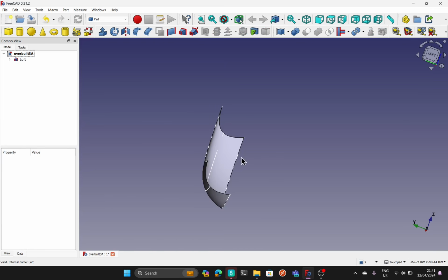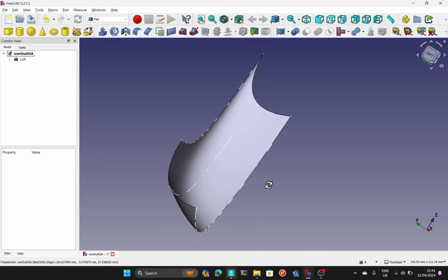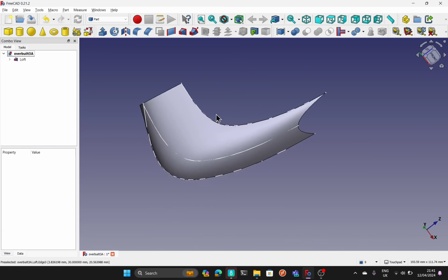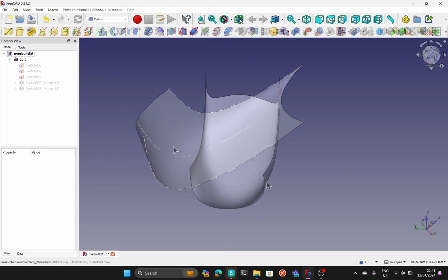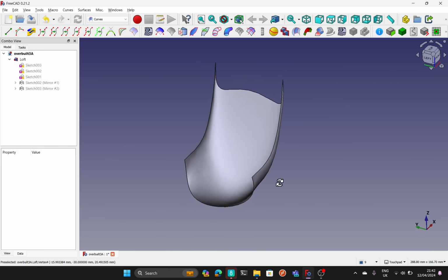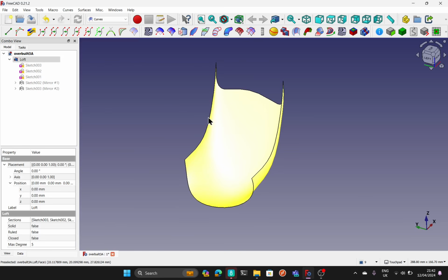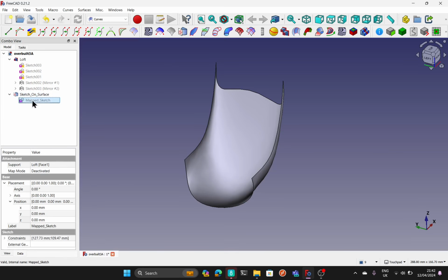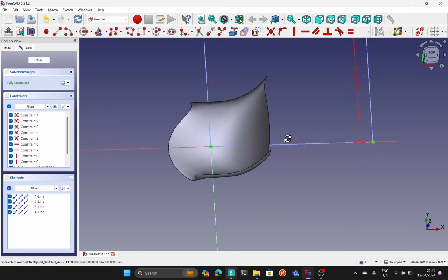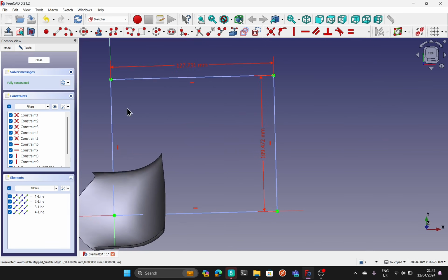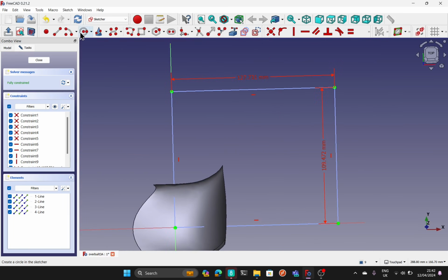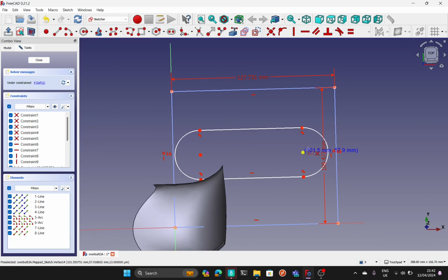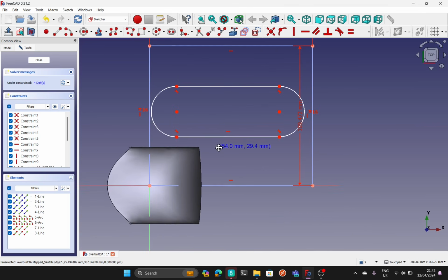There is one problem with using a curves workbench, curve on surface process for doing this. So using that curves on surface tool. So looking back to the original loft, if I take the loft, click that, and use the sketch on surface, you get that sketch on surface there. Double click the sketch. If I place geometry within this section here, let's say a slots geometry, something like this. So we've got that there.